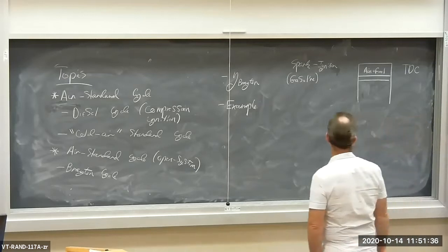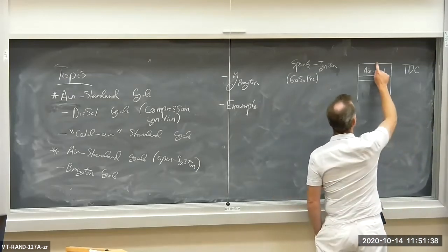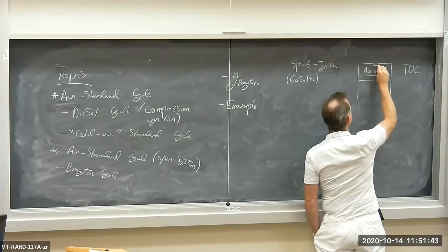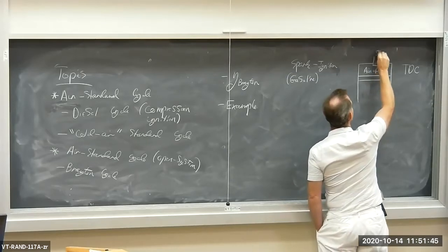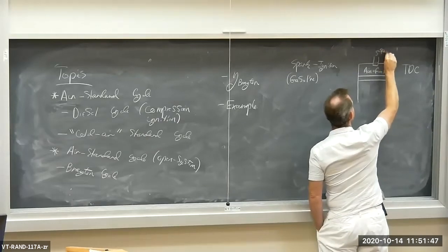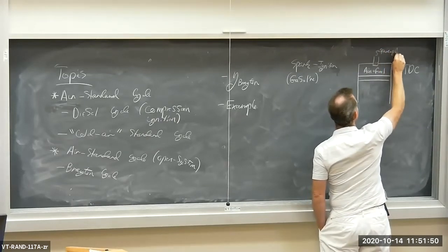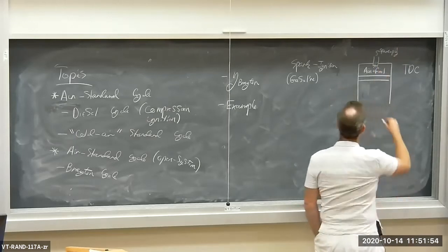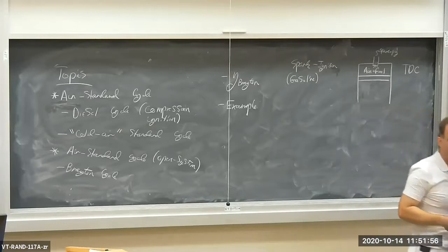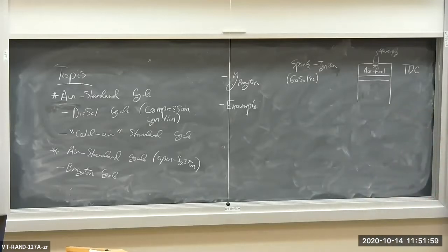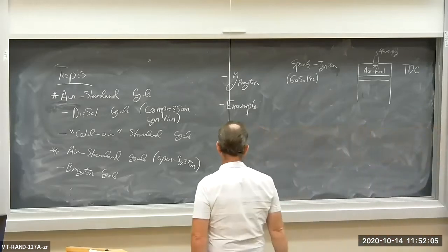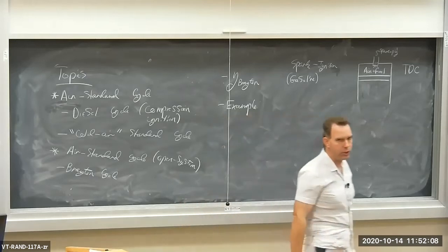Isentropic compression, if you like. And we have a little spark plug up here. And a little spark occurs, and the air and fuel start to burn. Now the air and the fuel burn so quickly that we can model the reaction, and therefore the heat addition, as one of constant volume heat addition.